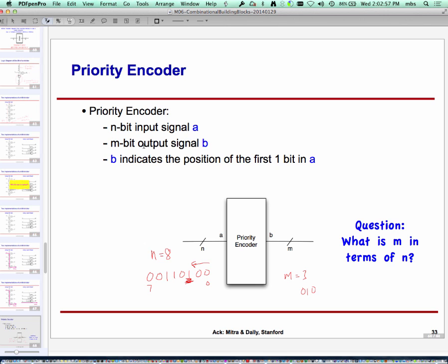Now, last year I had given a problem which was a variant of that, and I recall there were 3-4 students who got design costs which were roughly 2 to 2.5x better than what Logisim had produced. The reason is that Logisim only does sum of products or product of sums, and oftentimes by factoring things out more and having more than 2 stages in your logic, you could do better. Unfortunately, there is no single recipe, and of course, there is no particular known answer short of checking things exhaustively.